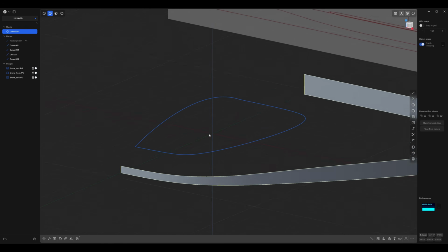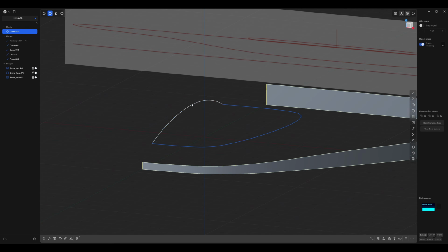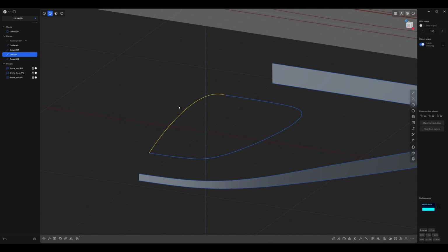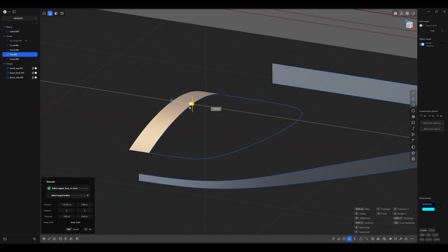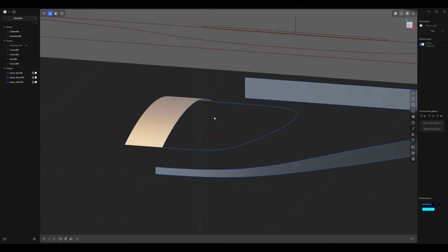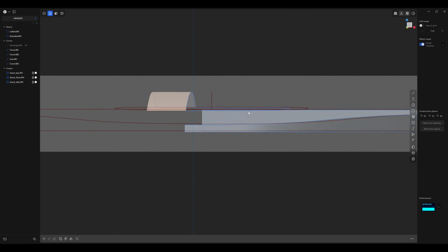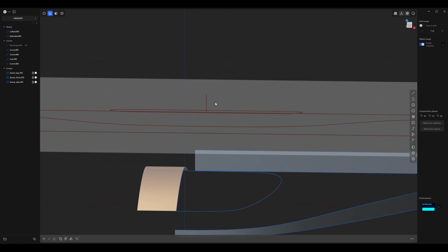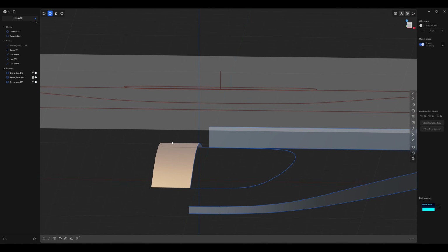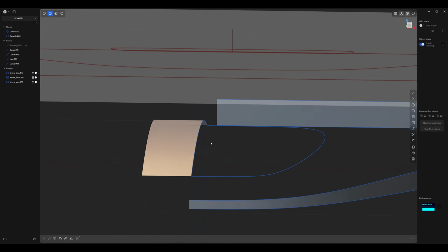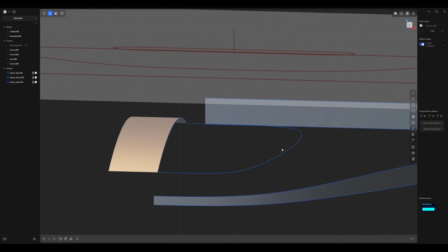This one has a slightly different process since we need some curvature here and continuity. You want to select this curve, press E, and we're going to extrude it towards the left. The reason is that this is going to create a surface kind of arching over and it doesn't have any information in what kind of continuity it'll have once it reaches the middle. And that's important when you mirror because it needs that continuity from left to right in the center area. Otherwise, you get a seam.